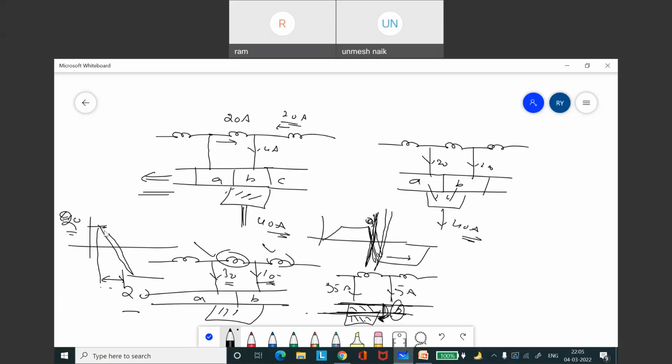But because of the shift in MNA, there will be an EMF in these coils at the poles. So instead of the current going from plus 20 to minus 20 within the commutation time, it will take more time. Because of this difference in time, the remaining current has to be taken out through the air gap, resulting in a spark.